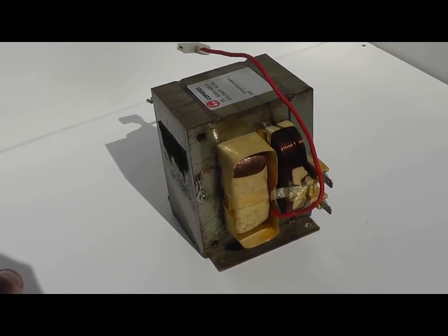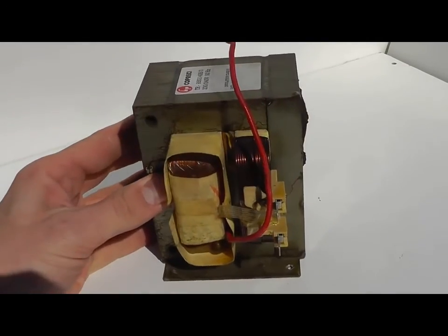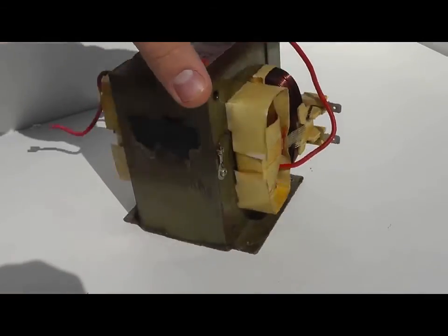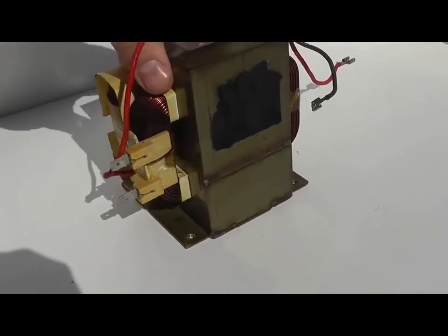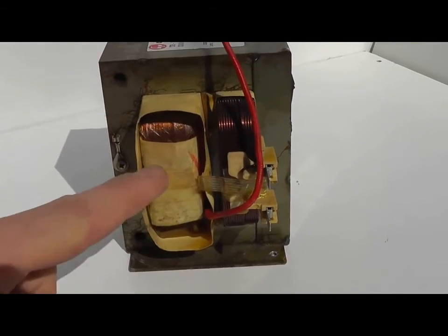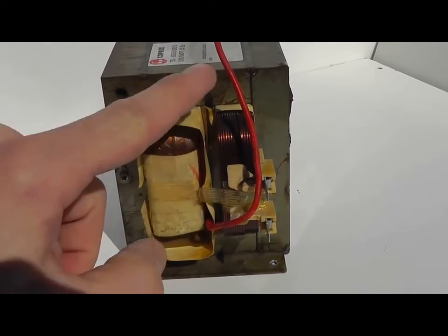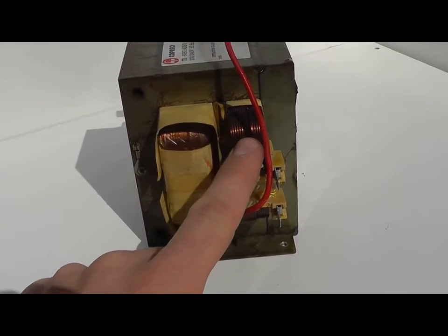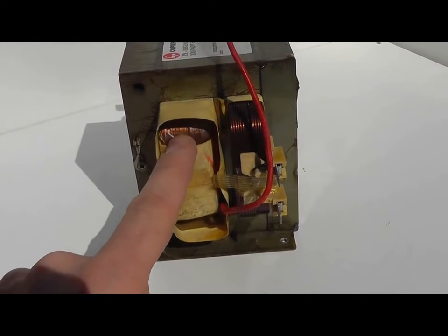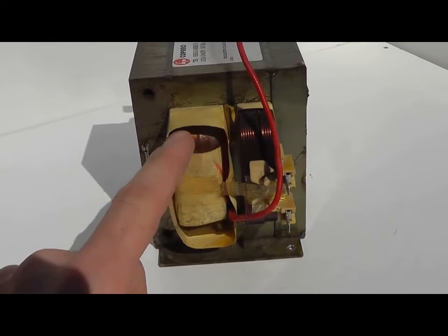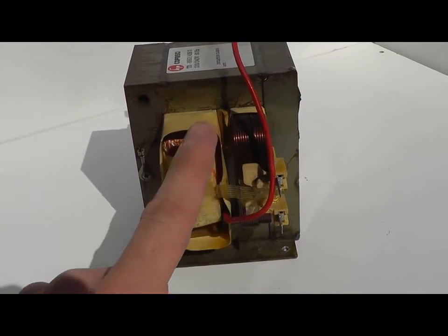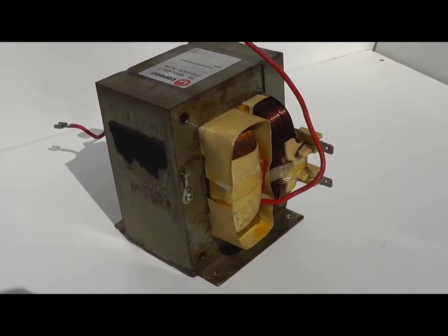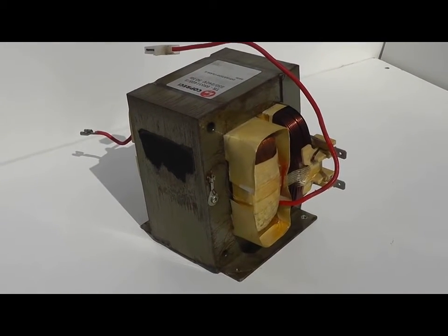In this video we're going to be looking at transformers, and here's an example from my microwave oven. It consists of two coils, a primary and a secondary, and these are surrounded by a very substantial piece of iron. The iron actually goes through the middle of these two coils, and this is something we call an E-core. It forms an E-shape with an end plate on it. The primary is much thicker wire because it carries more current, and the secondary has a lot more windings on it, and we'll see why later. But basically this transformer has 240 volts in and around 2000 volts out. It's what we call a step-up transformer. So what we'll do is have a look at how does this thing work.